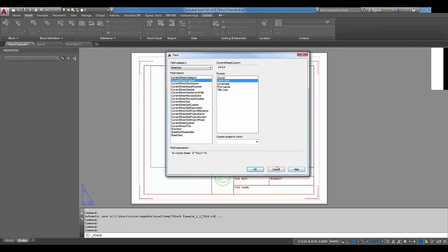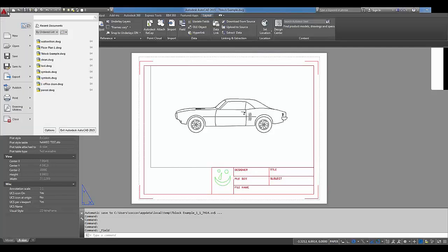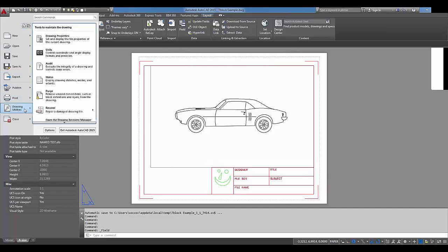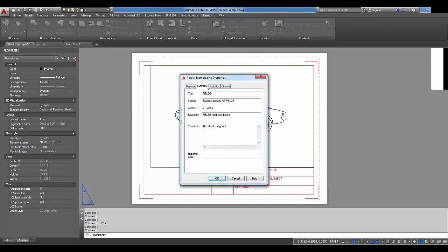And so if I go into AutoCAD here in my drawing, I've gone under the application menu, drawing utilities. We have drawing properties. Selecting that, we get this dialog. It looks very similar to the one I just right mouse clicked over my file. And you'll see that we have the title, subject, etc., all of these items which I just pointed out to you, as well as some statistics about the drawing.